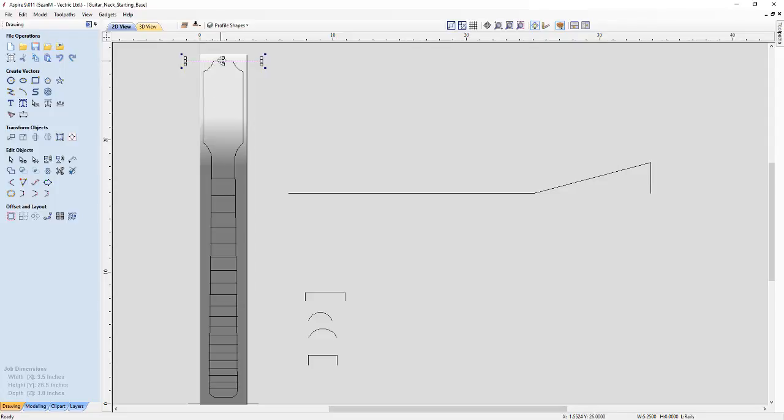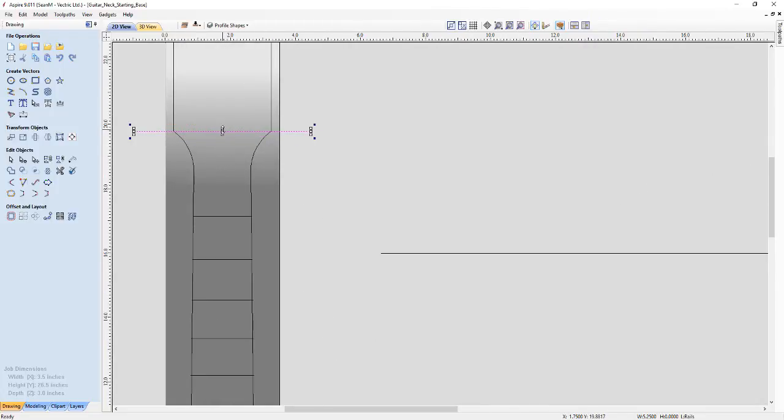And then I'm going to drag down and create a copy of this to snap at the center of this part of the actual headstock itself. So I'm just going to drag the center point, hold control and drag it along the line that you can see. When we get to this point we should be able to hover our center point over the edge nodes, and you should be able to pull back and snap that in the center like so. And again, I'm going to drag a copy of that while holding control. Just make sure that we've got somewhere we can snap it to on a node like so, and then drag it back to the center, and we'll be alerted by the software when we can snap it into the central position.